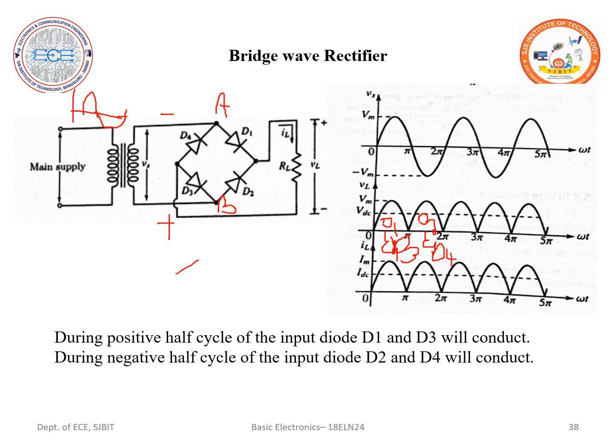That is, if I represent this during the positive half cycle, my diode D4 is an open circuit, my diode D1 is a closed circuit. Similarly, my diode D2 is an open circuit and my diode D3 is a closed circuit. So this is my D1, D2 and D3. This is how my circuit is going to be during the positive half cycle, and during the negative half cycle, vice versa. This is going to become a closed switch and these two are open switches.